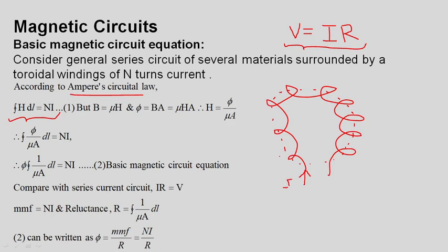So what happens is, for this circular Amperian path which you have considered, for every winding the current will enter and come out. There are N windings, so N times the current will enter and come out. So that is Ni. We write it as I suffix e, the enclosed current. In Ampere circuital law, that current I is the total current, how many times that current has entered that Amperian loop. So the total is Ni.